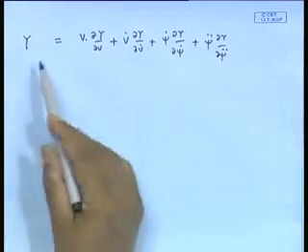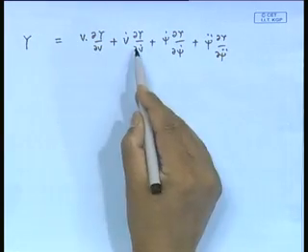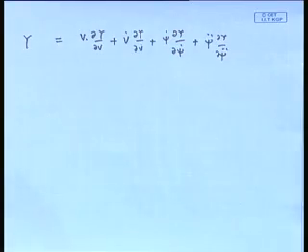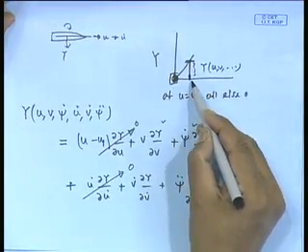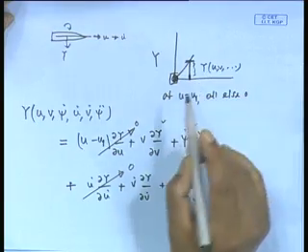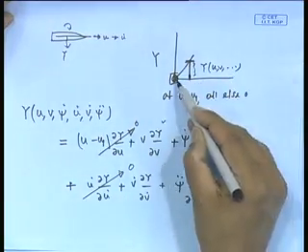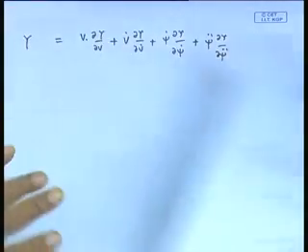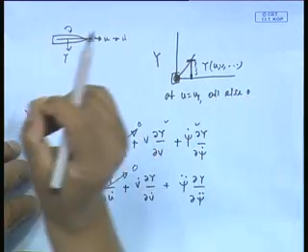So, remember here these are necessarily very small values. Why small values? Remember that my initial values were 0, 0, 0, 0, etc. Final values are V dot, psi double dot. They are all just small changes about the mean value. In fact, U minus U1 is also a small value, because U was, let us say, 10 knots, U1 would be 10 plus or minus something.